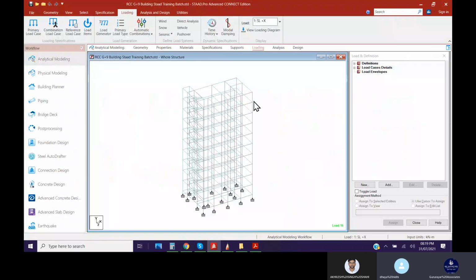Only thing is the weight of the entire structure will get reduced. Imagine if the beam's weight, the wall weight above the beam, is reduced, then what will happen? Beam size will be smaller. Imagine if the same weight is transferred to the column, it also gets less axial force, and the footing also becomes less. So all the sizes of beam, column and footing will become small if you use aerated lightweight bricks.